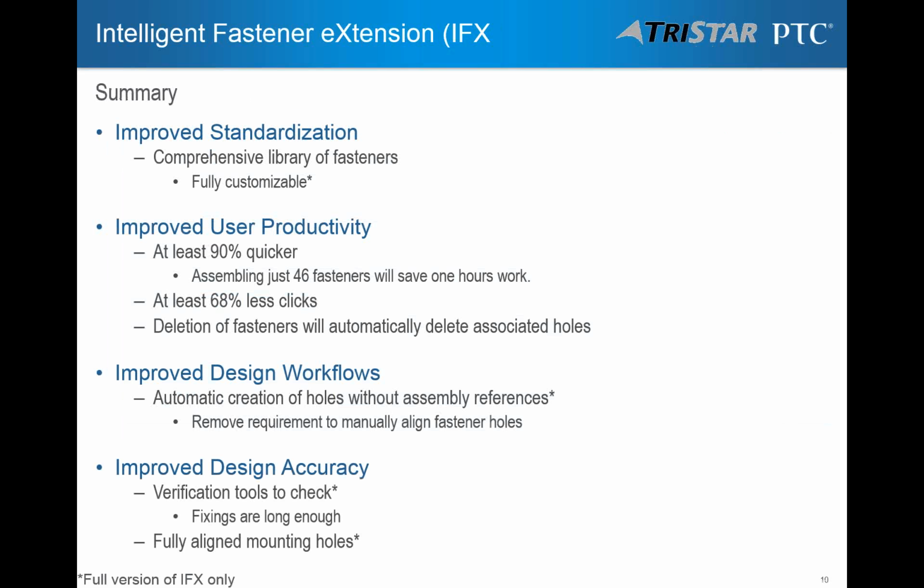So in summary, this is an improved standardization, a comprehensive library of fasteners which are fully customizable with the full extension, improved user productivity, 90% quicker, 68% fewer mouse clicks, and if any fasteners have been deleted, it will automatically delete the holes that were created. There's an improved design workflow, the automatic creation of holes without assembly references, and a removed requirement to manually align fastener holes. There's also improved design accuracy. There are verification tools to check that the fixings are long enough and that the holes are fully aligned.